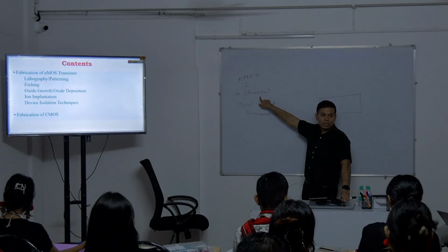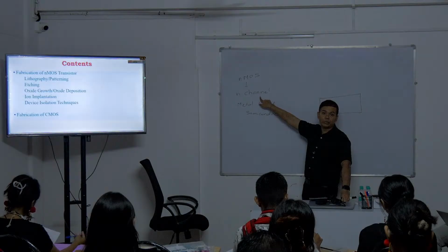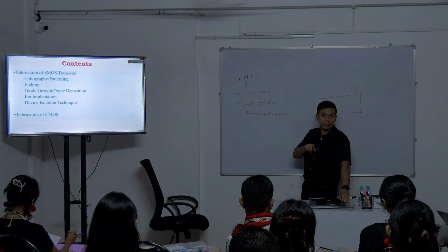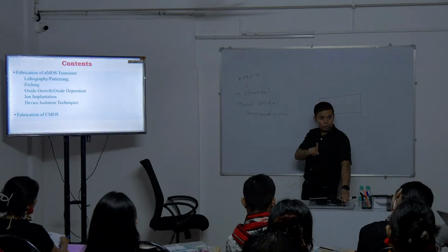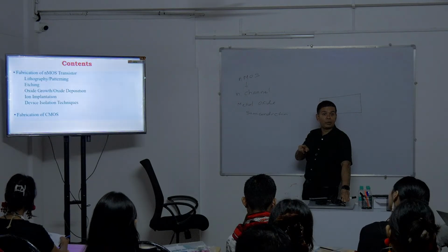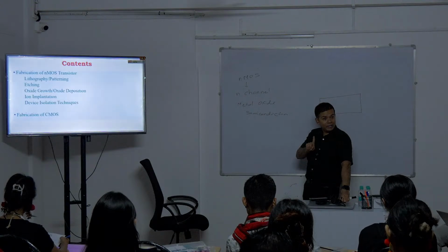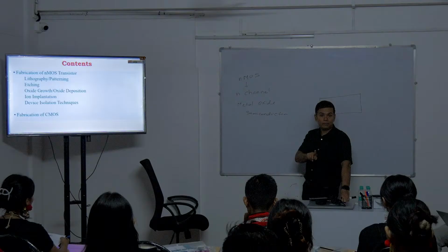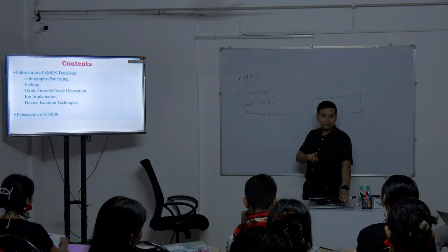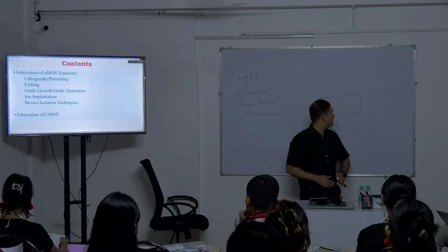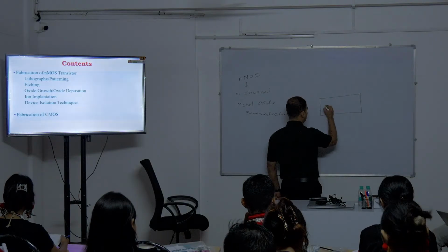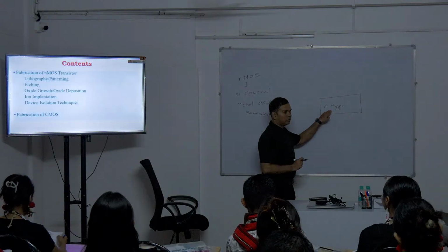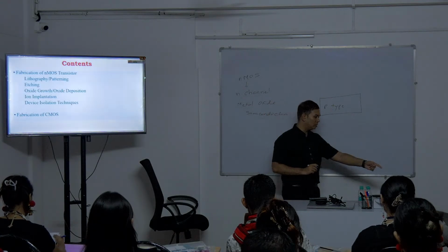Electrons, right? And electrons are minority charge carriers or majority charge carriers? Minority charge carriers. So majority charge carriers will be holes, and holes, they are of P-type or N-type then? P-type, right? So the substrate will be P-type, right? So that is the very first step that we start the fabrication from, right? So go to the next one.